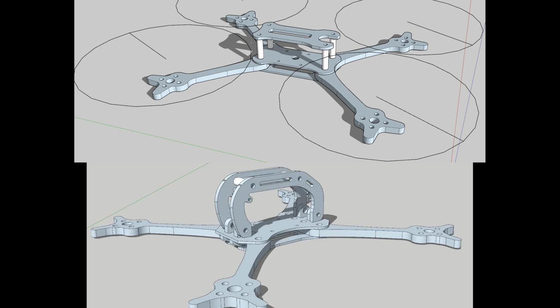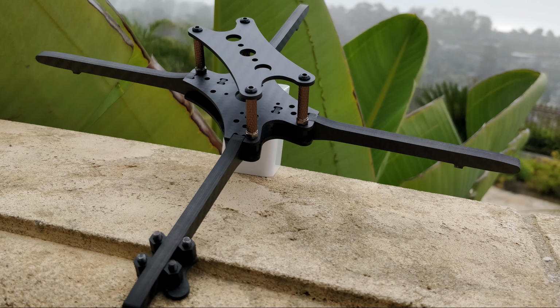But one other thing I want to ask, which you bring up, is frames that have vertical arms. I've tested vertical arm frames a lot, different designs. I basically can't get away with just using a vertical arm that isn't tied across to the other arms. There has to be some cross bracing of the arm.